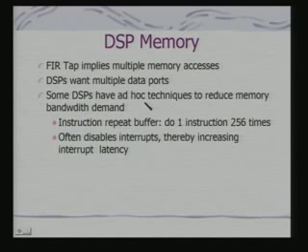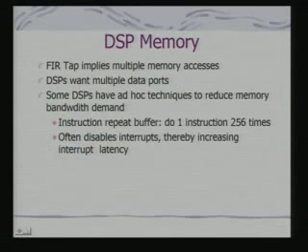Many DSPs implement what are called ad hoc techniques to reduce memory bandwidth demand. One is the instruction repeat buffer. So what is the instruction repeat buffer? I can put a set of instructions, and if these instructions are repeated, then I need not go back to the memory to fetch the instructions. I have already fetched the instructions, put them in a buffer and execute them in a loop. Obviously this would reduce the loop overhead, and this design issue comes up from the demands of repetitive numeric calculations of the DSPs. Often this blocks interrupts, thereby increasing the interrupt latency. This trade-off is an important point to note.